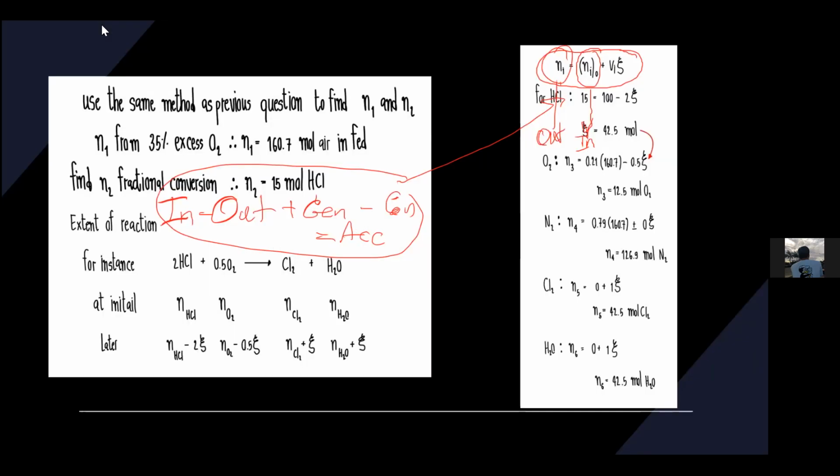Input. And also the term of extent of reaction, nu_i xi. nu_i xi means generation and consumption. That's right. This is output equal to input plus the term of reaction, the term of generation and consumption. If nu_i is for a reactant, it should be consumption, that's why it should be negative.